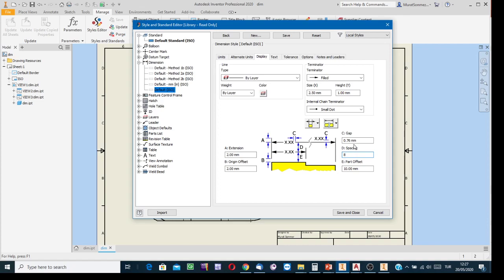For underlining purposes, in case the model is in the wrong size, the dimension on the projection is to be shown not with the wrong value but the correct value, so the dimension is to be underlined. For having the allowance for the underlining symbol, such a gap is necessary in ISO format, less than 1 millimeter. This is okay for me.